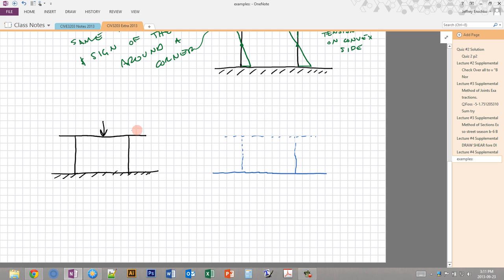Okay, so now we know that this top beam is going to bend down. So what if we assume that it's going to bend down like this? That seems like a reasonable assumption. We know that the fixed ends remain at 90. And so now if we wanted to join this, this twists out, so this is going to have to come back like this to meet the fixed end. But okay, that remains 90. But we have a suspicious situation here, because we have tension on the outside here, but tension on the inside here. So this corner is not compatible, right? Because we have an opening on one side and a closing moment on the other side, and there's no point moment here. So this is an incompatible corner.